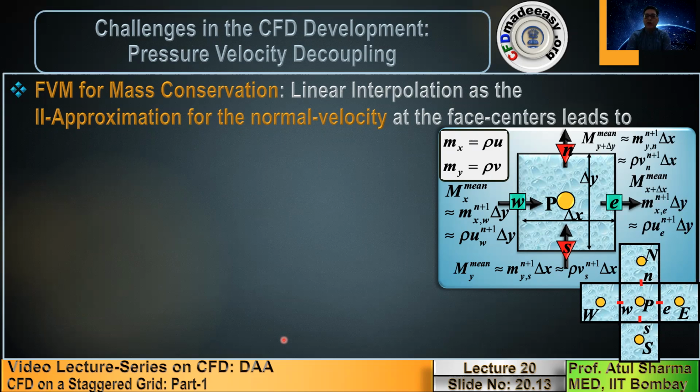The mass flow rate based advection transport, which corresponds to enthalpy flow rate in energy transport, can be extended to momentum conservation for momentum flow rate. And I had mentioned that the advection scheme presented in the previous topic on computational heat convection can be directly extended. So these are the things you can extend: the diffusion and the advection.